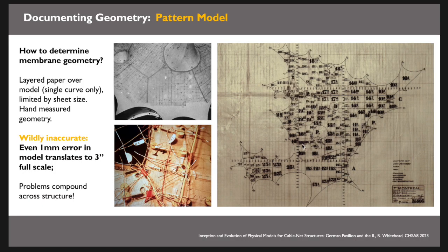From that hand measurement, they would go back and they could then draw what looks to be a plan. Honestly, this is so much trickier than what I just described, because they would take general dimensions, verify it with photogrammetry. They would then project the photogrammetry on a screen, make sure that what they projected on the screen was in fact to a proper scale. Then they would draw by hand on top of what was on the screen. Then from what they drew by hand, they would convert back to this one particular drawing, which was a 1:200 plan drawing of the patterns. If that sounds crazy and accurate, it was.